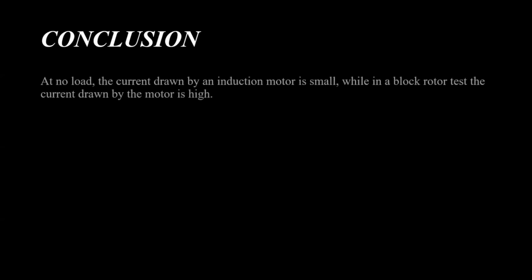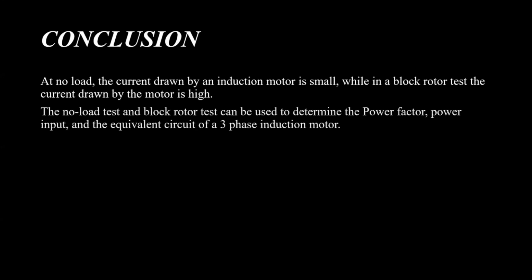For the conclusion, at no load, the current drawn by the induction motor is small, while in the blocked rotor test, the current drawn by the motor is high. The no-load test and blocked rotor test can be used to determine the power factor, power input, and the equivalent circuit of a three-phase induction motor.